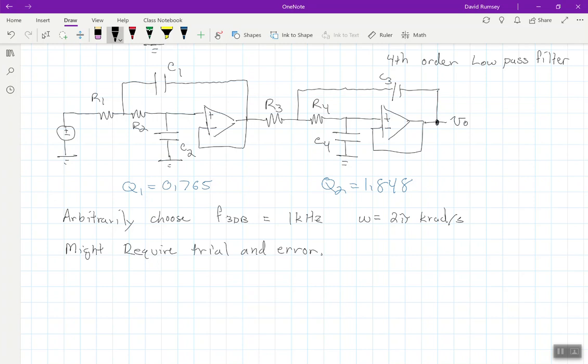And the reason is, well, you have to pick a value for R1. What I'm going to do here, and this is something that we often do to make life easy, is pick certain components to all be the same value. I'm going to just let all the resistors be equal to 10 kiloohms. Now, it doesn't mean they have to be 10 kiloohms. You could have chosen 15 kiloohms, 12, or 1 kiloohm. And actually, the 10 kiloohm choice that we made here might be wrong.